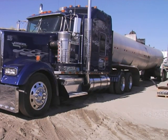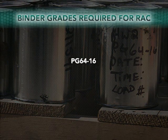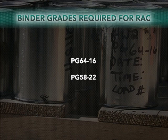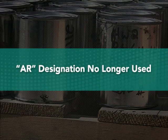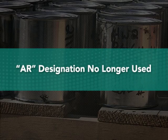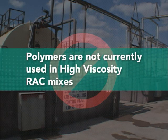The binder production process begins with the delivery of asphalt binder. The standard grades required by Caltrans for RAC are PG 64-16 and PG 58-22, although other grades may be used depending on the prevailing climate. PG-graded asphalts have replaced the aged residue or AR designation. Other storage tanks contain the extender oils and anti-strip agents. Please note that polymers are not currently utilized in high-viscosity RAC mixes.